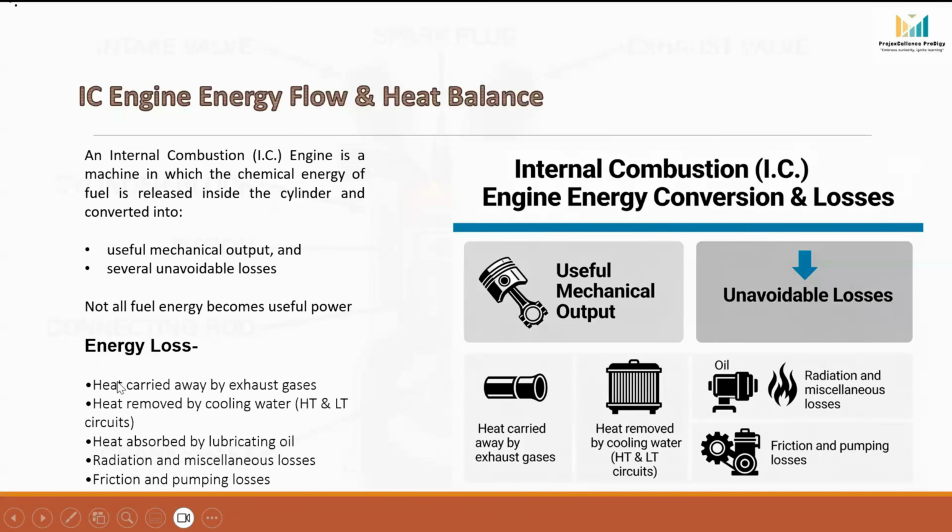First, the biggest loss is through exhaust gases. After combustion, very hot gases leave the engine, carrying a large amount of heat energy with them. Second, cooling losses. The engine operates at very high temperature. So, cooling water in HT and LT circuits removes heat to protect engine components.